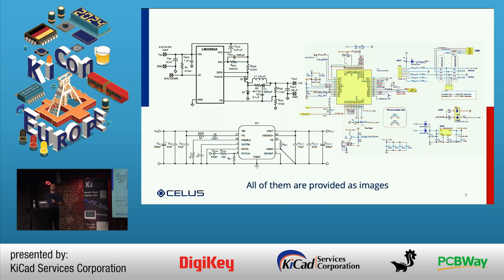That means if we're designing a new circuit, if we want to design a PCB out of that, at some point we'll have to take those images and capture them in a tool like KiCAD and then proceed with the development process after that. So there is a process here of looking into an image, finding the appropriate symbols in my library, and reconstructing this schematic in KiCAD in this case.